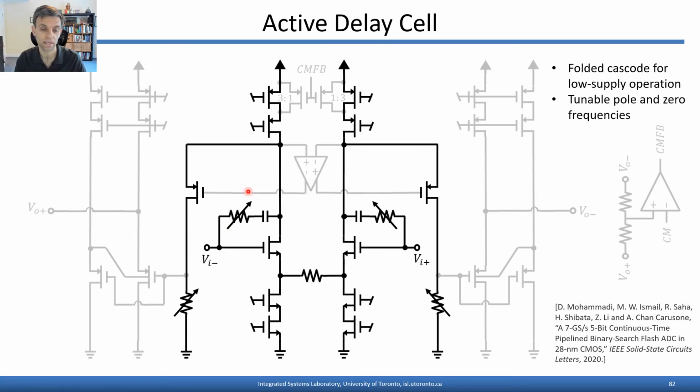In this case, the value of the resistor is just tuned to fine-tune the location of the zero in the right half plane and provide us that extra 90 degrees phase lag. But we're going for the all-pass response so that the zero location should mirror that of the pole location.